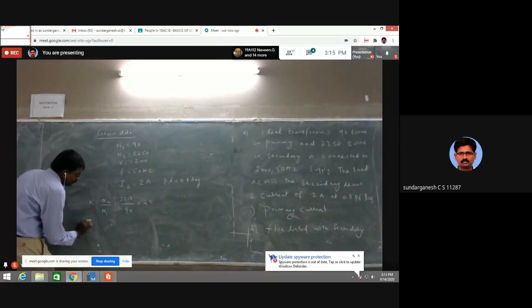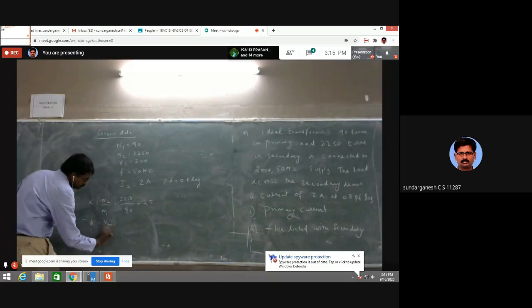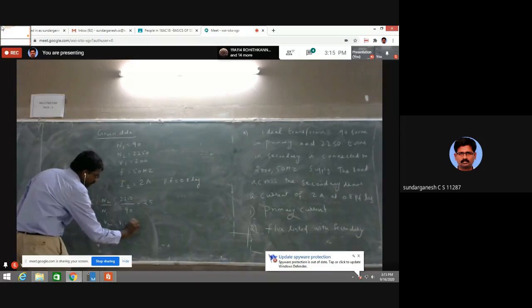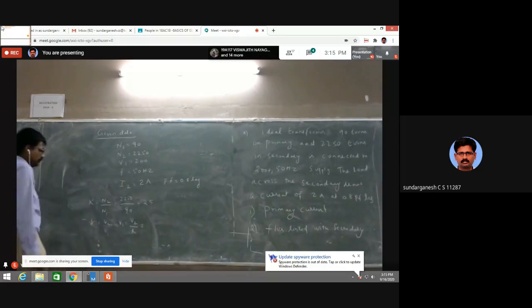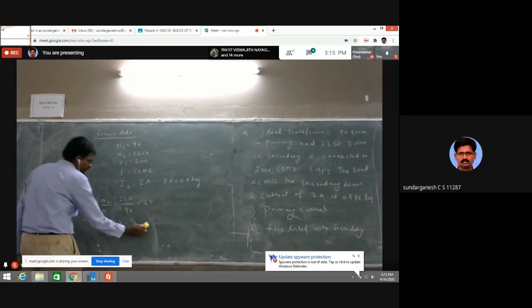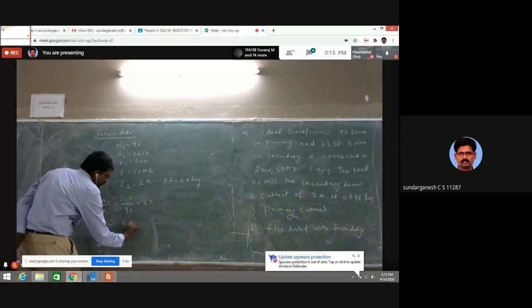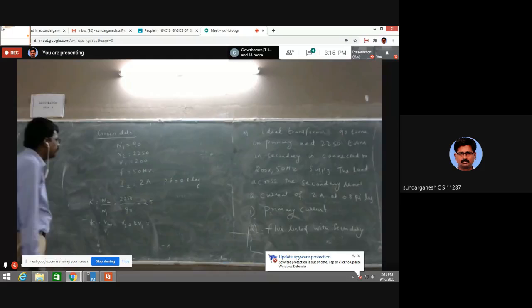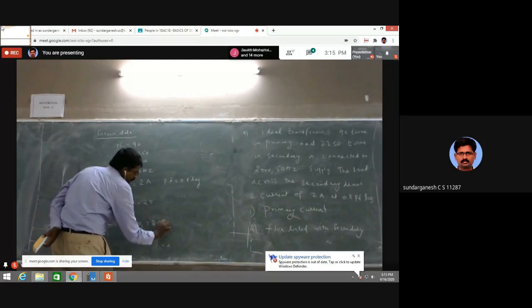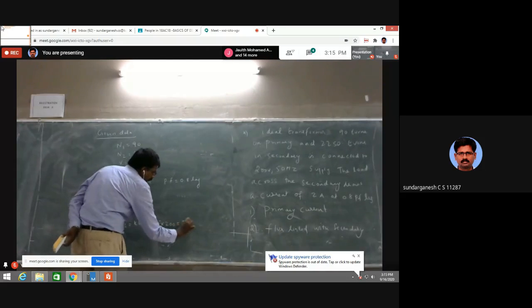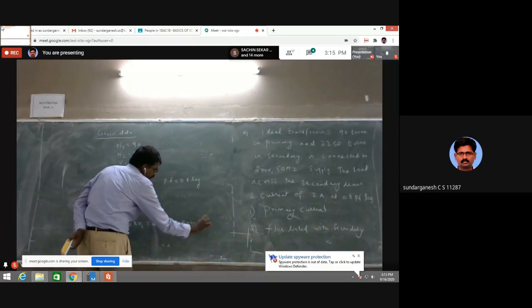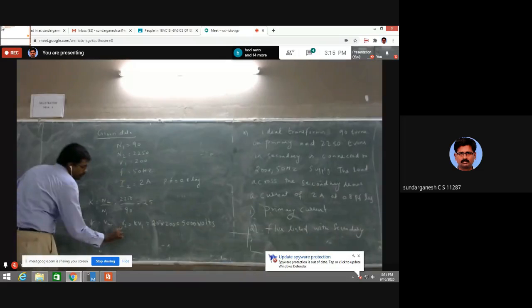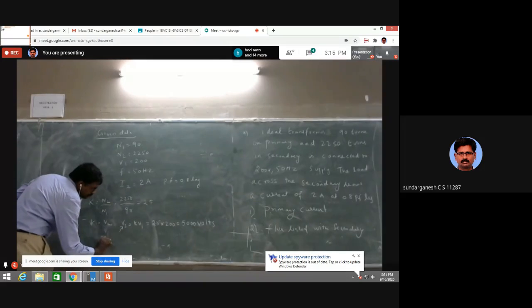K equal to V2 by V1, so V2 equal to K into V1. K is 25, V1 is 200, 25 into 200 is 5000 volts. So I have found the secondary voltage.